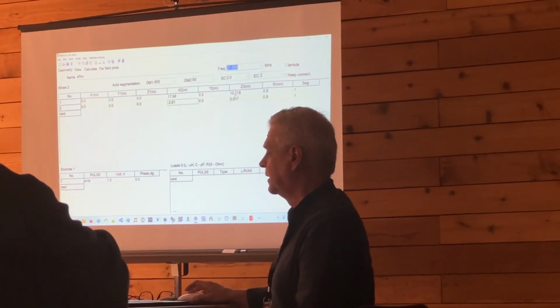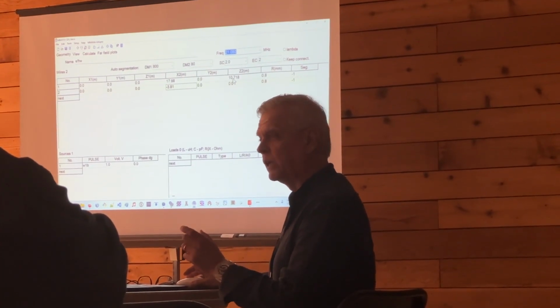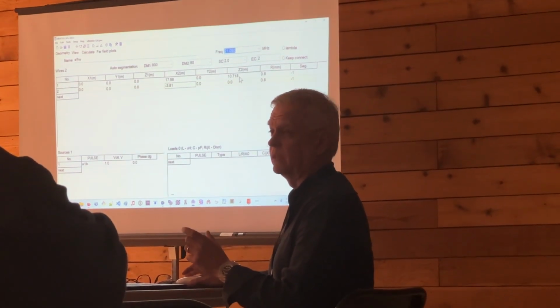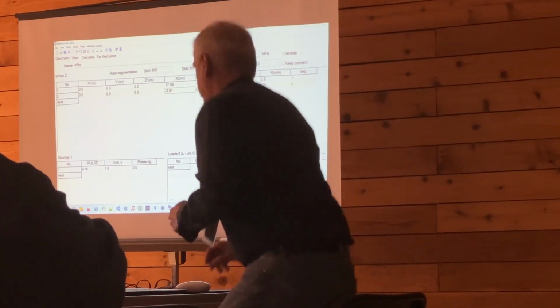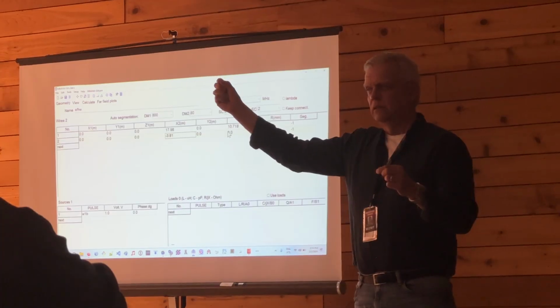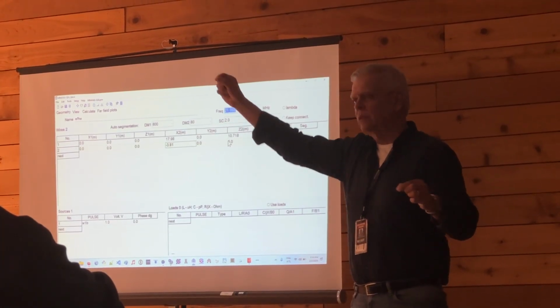And what about your Z? Remember, the Z was 10.218. Now it's saying, hey, the math will work better if it's 10.718. Okay? So in a nutshell, it's telling us, hey, cut your antenna a little bit long. Don't cut it at 67 feet. Give us a little bit extra.